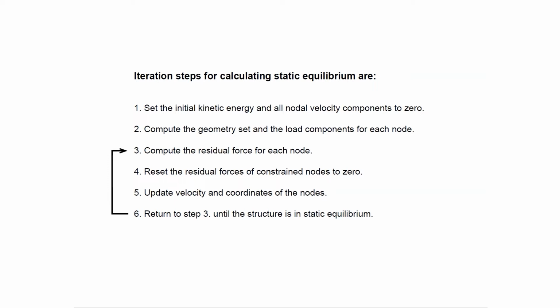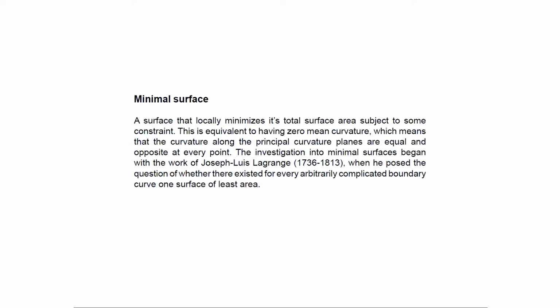It's very easy actually to set up these constraints so that we find this equilibrium. The residual forces become smaller and smaller, and at one moment, because we calculate it in a discrete way on a computer, we have to stop. So we cannot really go to 0, but we can go as small as we want. And that's kind of how this dynamic relaxation works. Our code that I will show you in Python does exactly this. I could in theory match each of these steps with each of the steps in the code. There are of course many things in between, but it just has to do with how we implement it in Python.